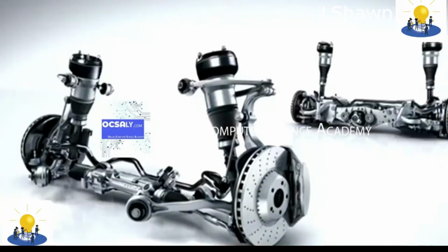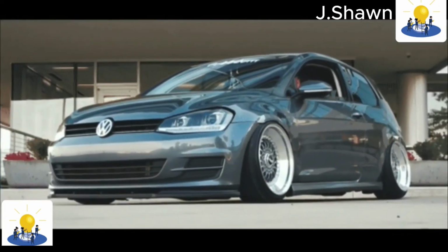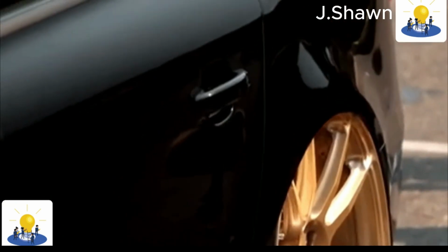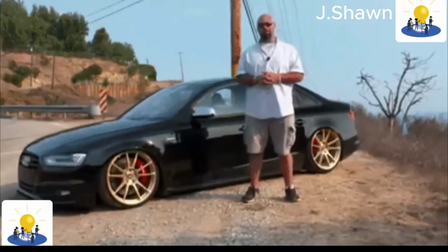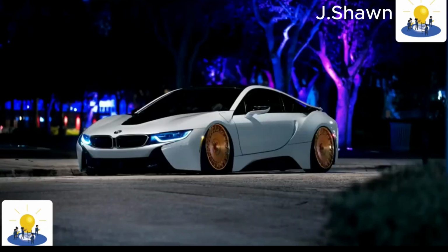These bars are typically in a trailing arm configuration, and the air spring may be situated vertically between a link bar or the axle housing and a point on the vehicle's frame. In other cases, the airbag is situated on the opposite side of the axle from the main link bars on an additional cantilever member. If the main linkage bars are oriented parallel to the longitudinal driving axis of the car, the axle housing may be constrained laterally with either a panhard rod or Watts linkage.